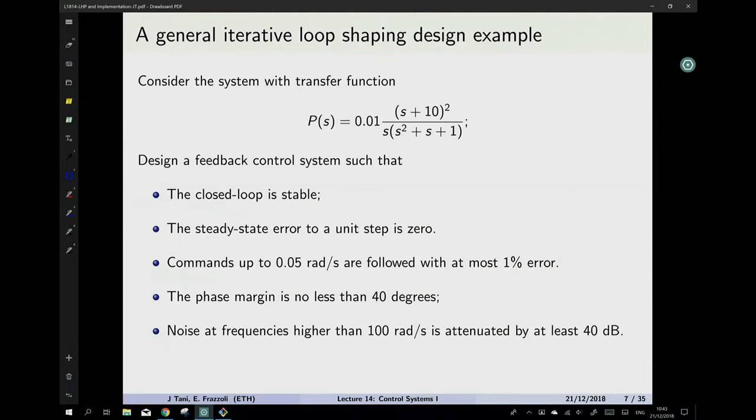There are poles and zeros in a transfer function, right? There's not much more than that. Poles and zeros and a gain, yeah, sure. Gains don't always get the respect they deserve. But anyways, poles and zeros. So the first thing you notice is it has a pole at zero and two stable poles, -1 plus or minus j, right? The solutions of s squared plus s plus 1. So as long as you have one pole at zero and you have the negative real part for the other poles, then you've got a stable system, open loop stable.